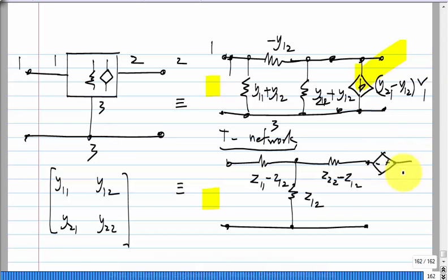And similarly, you can see that very easily for the Z parameter matrix. If you include Z21 minus Z12 times V1, that will also work. All that will do is it will cancel off this Z12 term here and then introduce a Z21 term. Earlier they were equal, so that was okay, but now you need them to be unequal. So the network is also asymmetric. But from this you can also see that there is an infinite variety of possibilities. You can keep on generating networks. The more important thing is to see in your context if some particular representation is more useful than others.